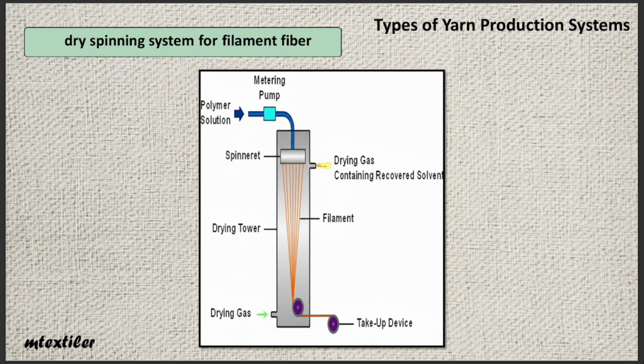The solvent in which the polymer is dissolved rapidly evaporates after exiting the spinneret. In fact, the filament encounters warm or dry air, which leaves the strand in solid form. The filaments are drawn by rollers in order to align the polymer chains and obtain appropriate strength and flexibility. At the end, a controlled heating stage is carried out to stabilize all the yarn properties.